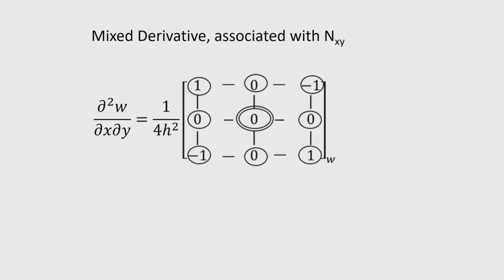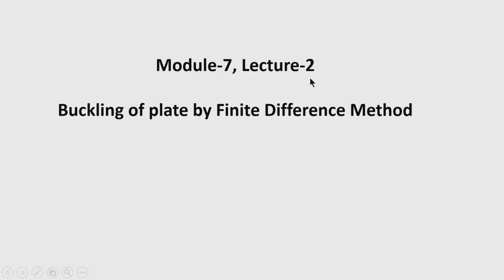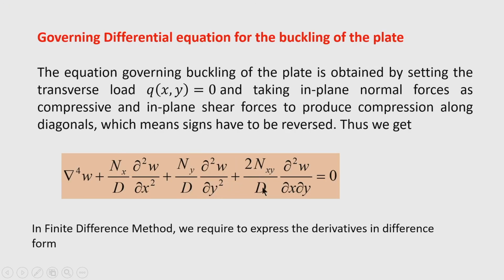Okay. So, the mixed derivative is also required, because if I consider the membrane shear force or shear buckling of the plate, then we have to consider the term associated with nxy that I have shown in this slide, that is nxy by d and del square w by del x del y. So, the mixed derivative term is associated with nxy. So, we should also know the finite difference form of the mixed derivative.